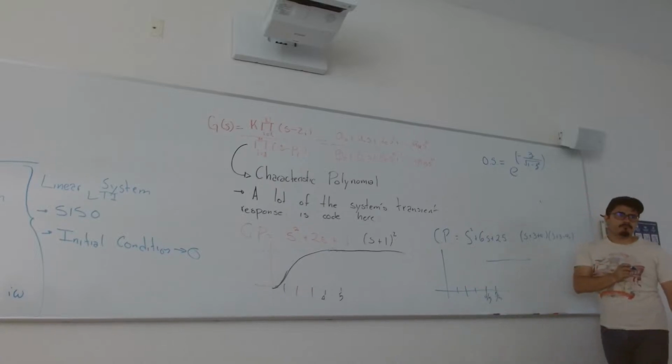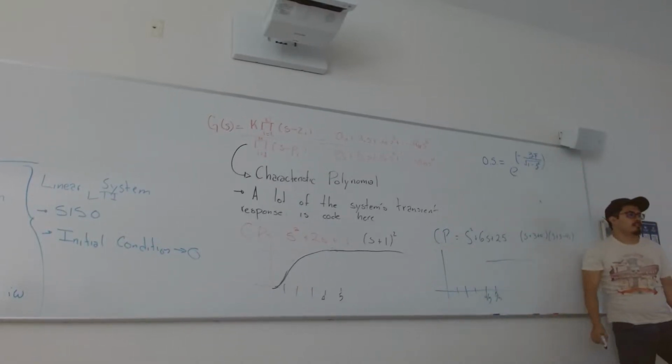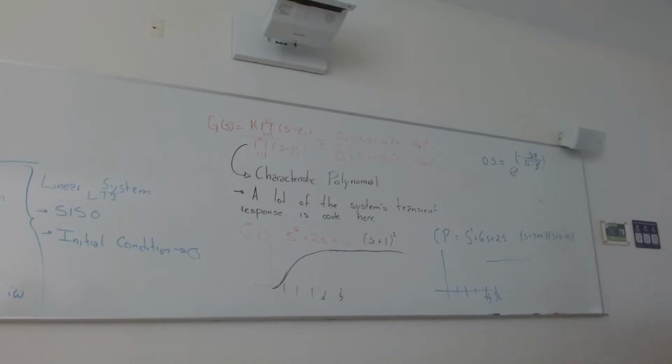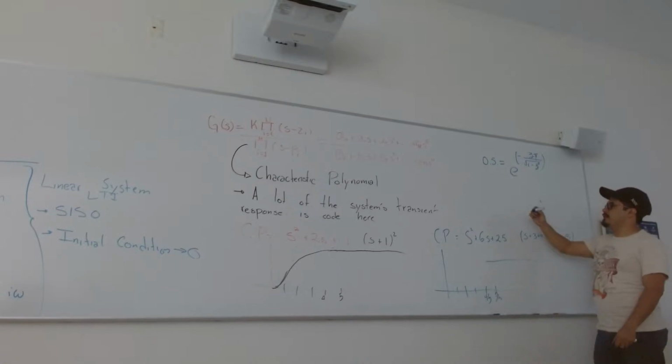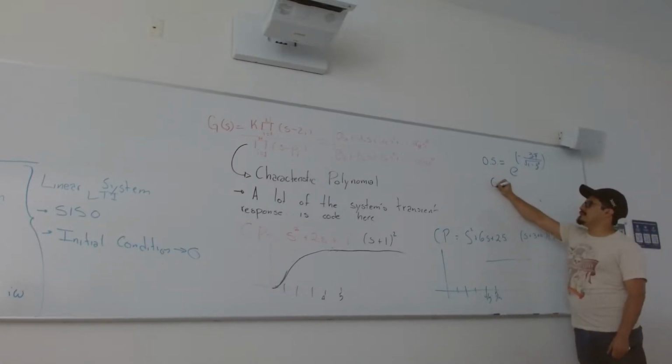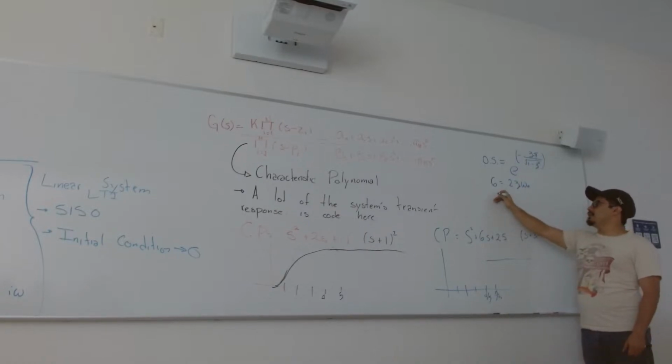Okay. Good? Underdamped. Do I have the damping factor? How do I get the damping factor? With the natural frequency. I'm going to say that 6 is equal to 2 times this guy. And we know that the natural frequency is the square root of 25.